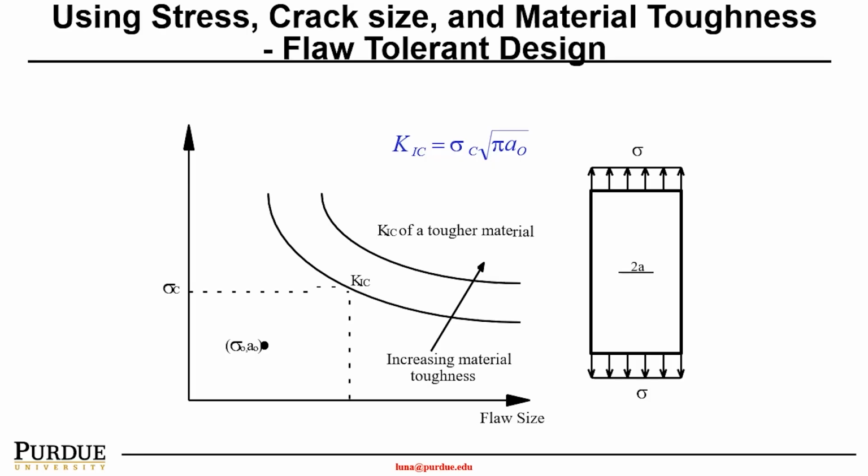If we look at the stress-strain curve, the material goes through linear elastic behavior, then reaches a plateau, then goes to the plastic region, and then you have sigma F, and sigma ultimate stress, or sigma yield. This is your ultimate stress, or what we call the strength of the material.